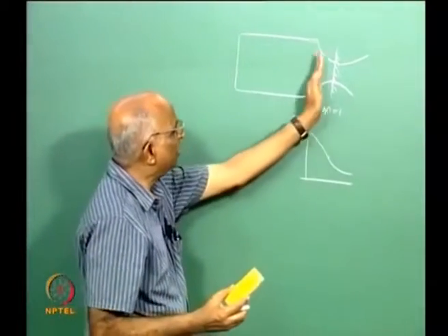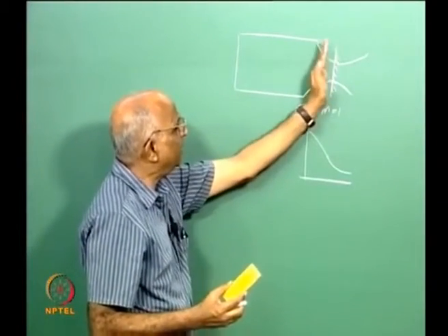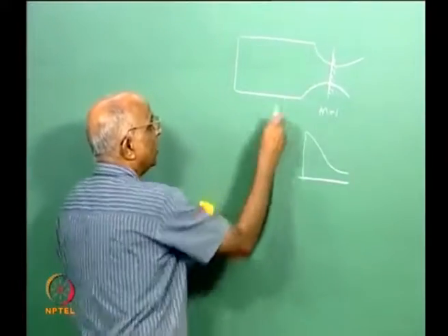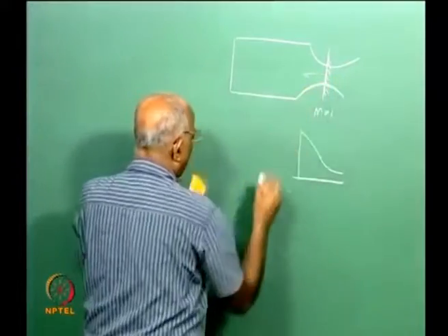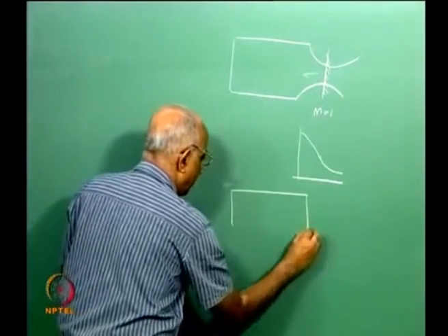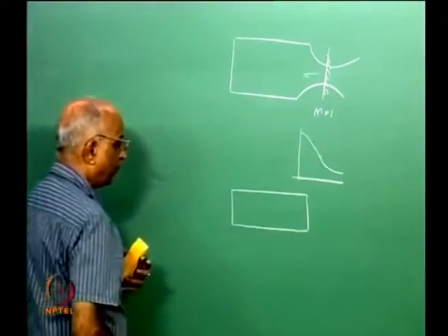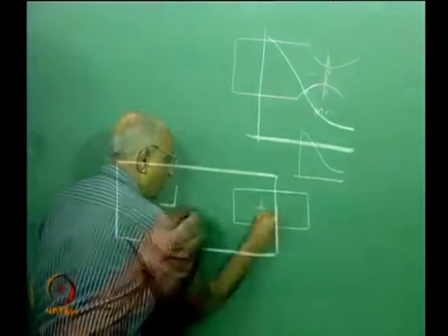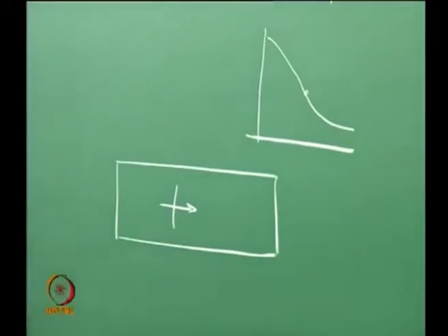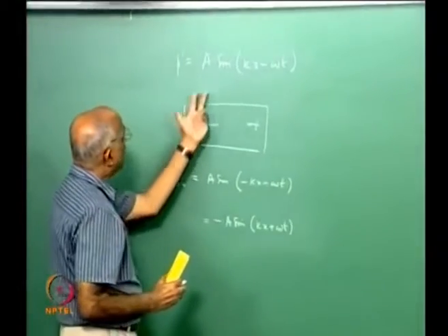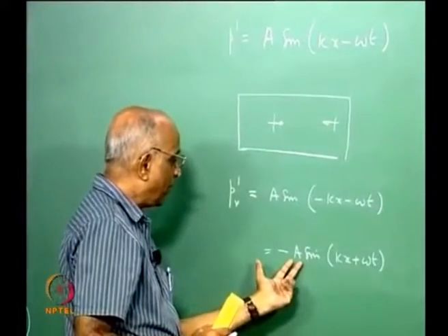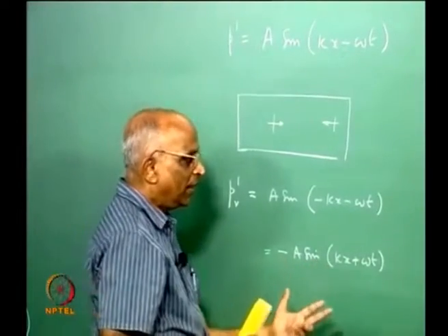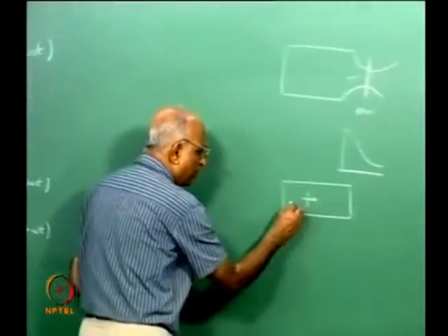There are so many changes in density that the wave, when it sees it like a solid surface, reflects back. Therefore, the chamber of any rocket chamber is like a cavity closed at both ends. Now, you have a wave which is travelling forward, and the forward travelling wave is given by a sin(kx minus omega t), the reflected one is given by minus a sin(omega t), and therefore, you have these periodic